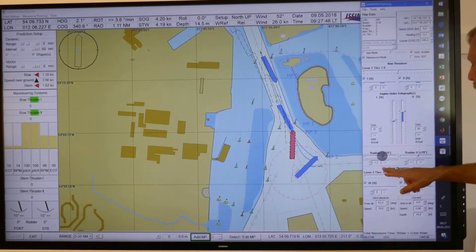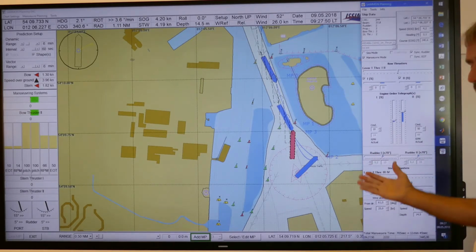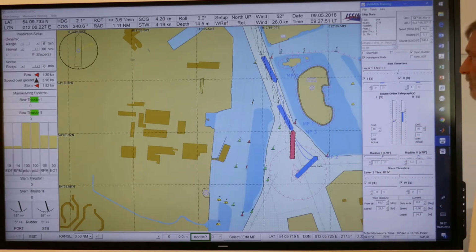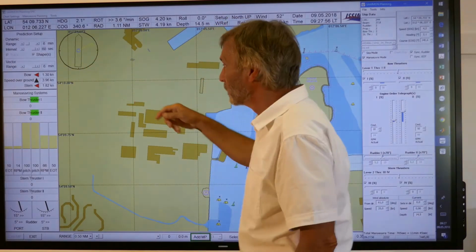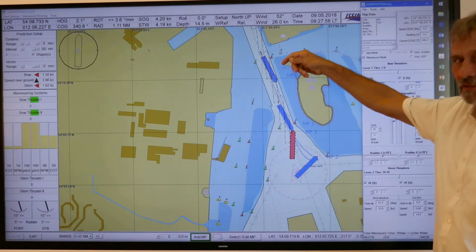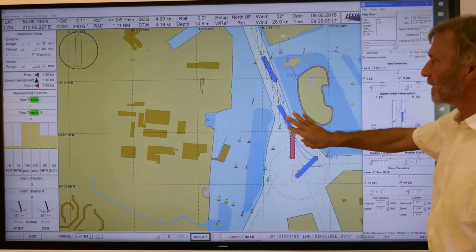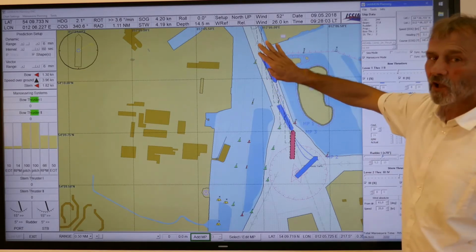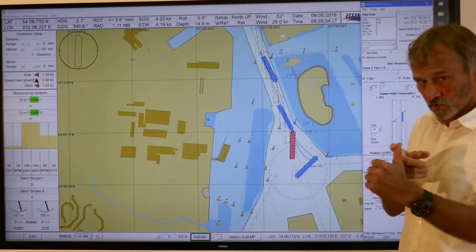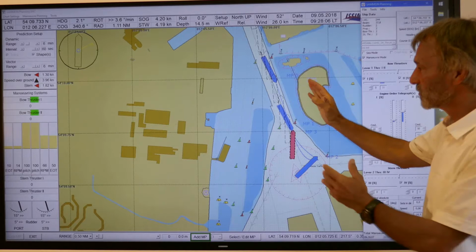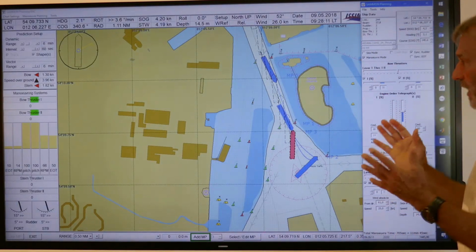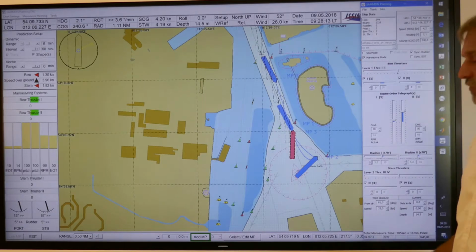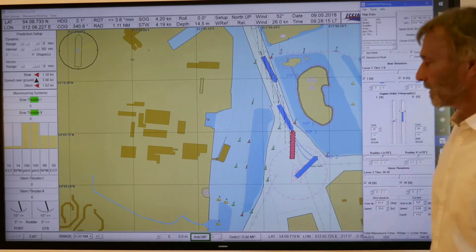So you can tweak a little bit around that to really adjust the correct rudder. Because we have strong wind, you see the wind is blowing with 25 knots from this direction. Normally the passage is only possible with a drift angle, what you can see here, so it's just suitable to be accommodated into the channel, and also with a certain rudder.